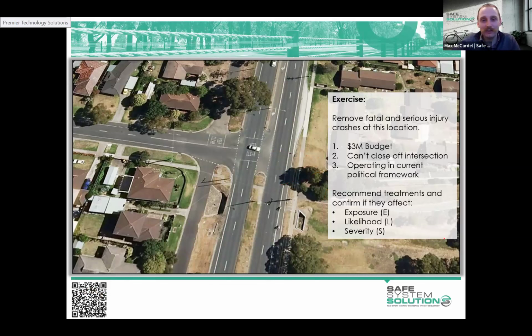I'm actually really bad at drawing seagulls. It's this idea of if you were turning right out of here, right? So say you're a vehicle turning right out of here, you get this kind of acceleration lane. So this is kind of blocked off. It's just curbed. And then you pick up speed, pick up speed, pick up speed, and then you enter the traffic lane. Like that. The same thing is done for this lane here. Enters there. That's called the seagull intersection.